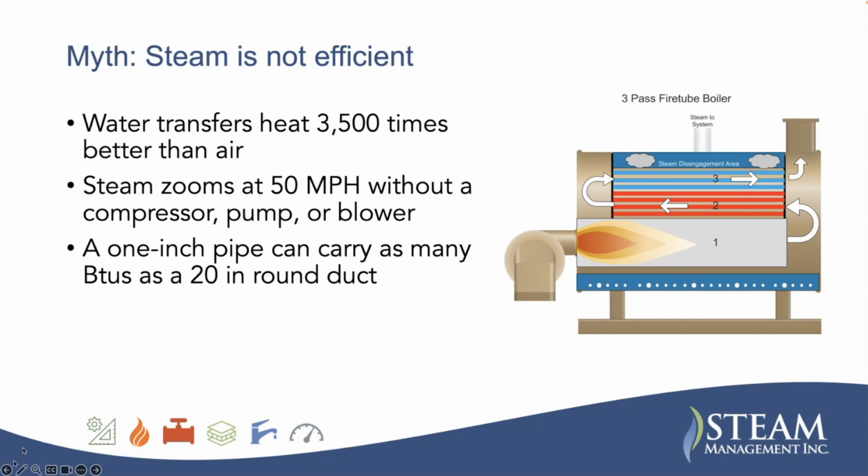Another thing is, you think about steam or hydronics, water transfers heat 3,500 times better than air. Steam zooms through, like I said, at 50 to 60 miles per hour, without a compressor, pump, or blower. A 1-inch pipe can carry as many BTUs as a 20-inch round duct.